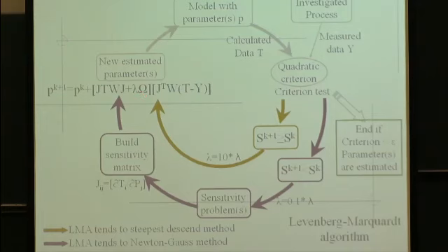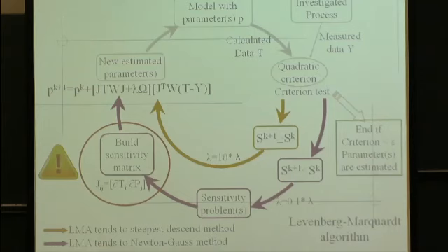It is basically here the Levenberg-Marquardt method, I would say. I define two sensitivity problems related to the two coefficients, eta and radius, that I want to estimate, to make this sensitivity matrix. This sensitivity matrix is the key of this method, or the success of this method. And then the new estimate, the new set of parameters, follows this formula, where G is the sensitivity matrix. I don't know what omega is. And here you will find the difference between the measured and calculated temperatures.